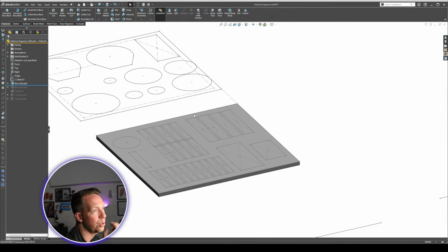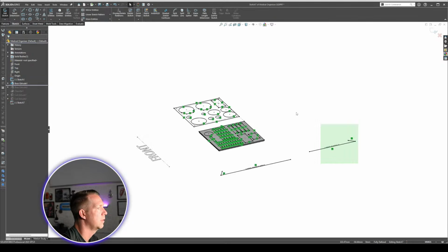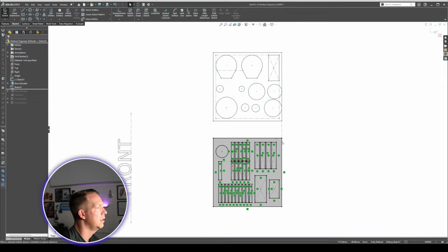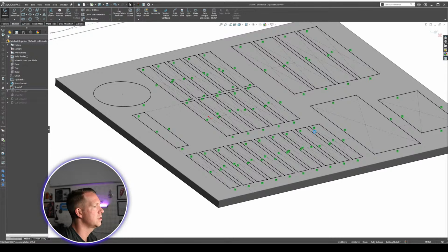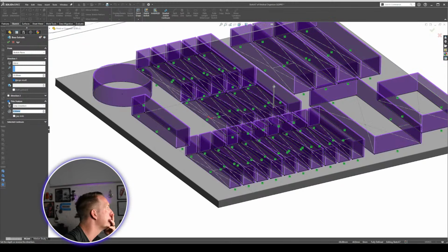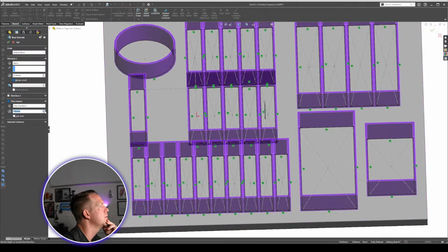could be to do extrude thins everywhere. So let's convert this sketch once again. Get rid of these, everything that we don't need. All of that. All of this. All right, so I've got all my edges. Let's do an extrude up. And I can change it to a thin feature. And so this is one way of creating all the walls without doing all that extra work.